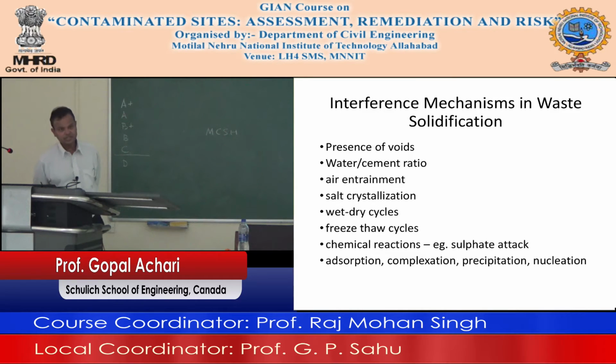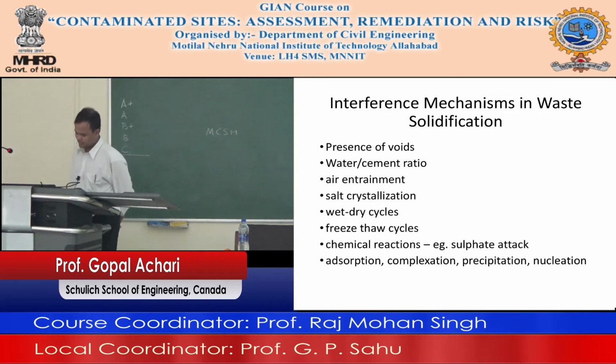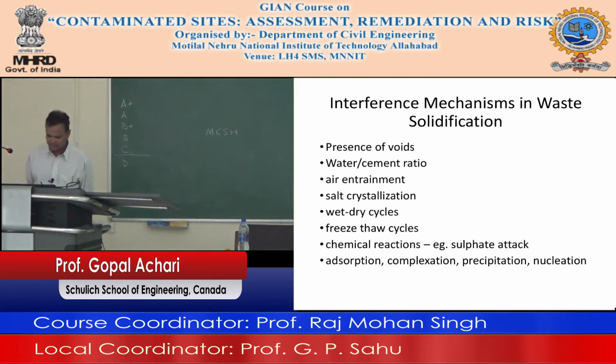Salt crystallization. Salt is another one. If your waste contains a lot of salt, the salt will crystallize and lead to cement not setting. Wet and dry cycles, freeze-thaw.